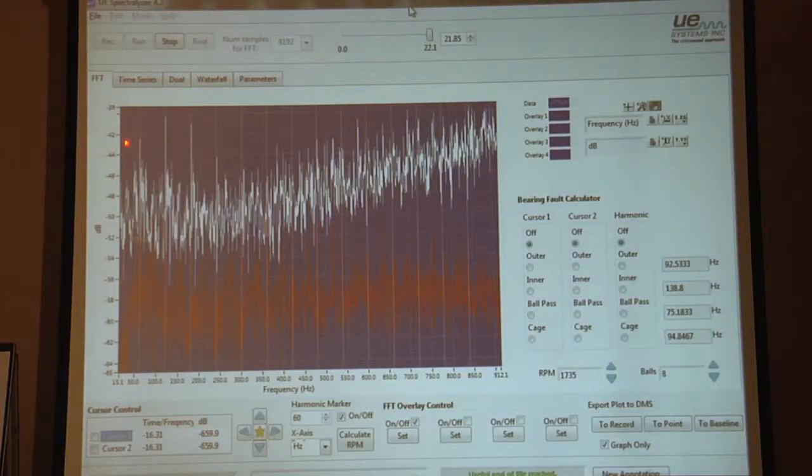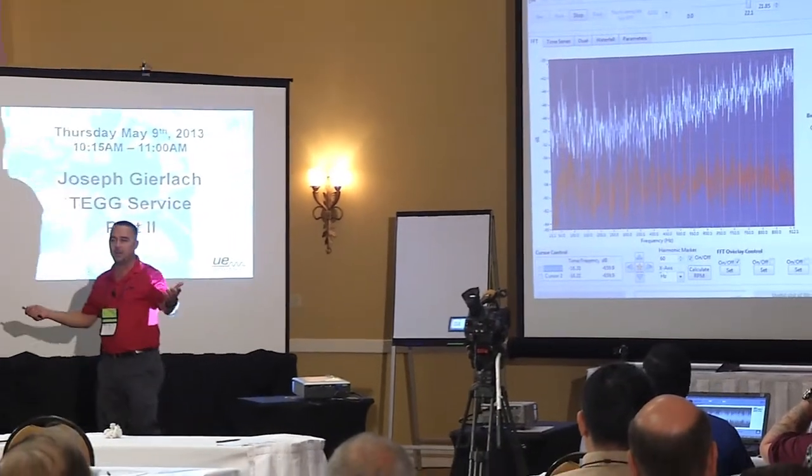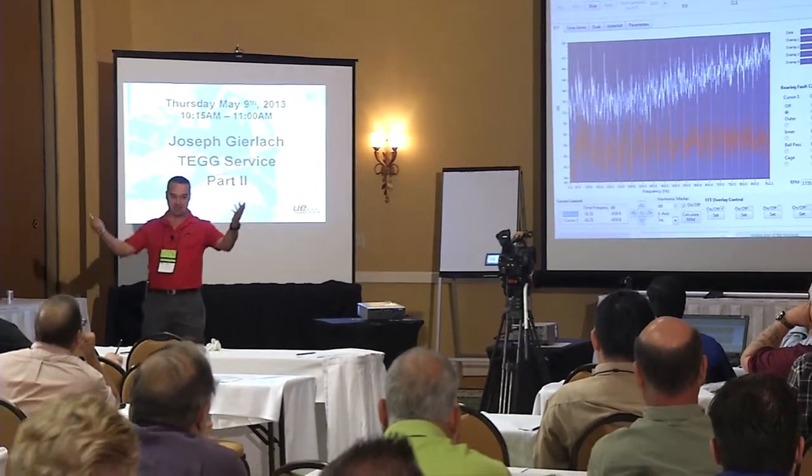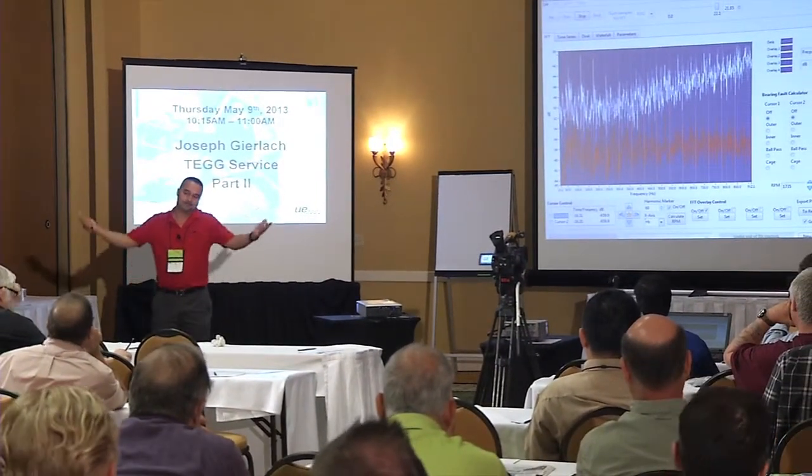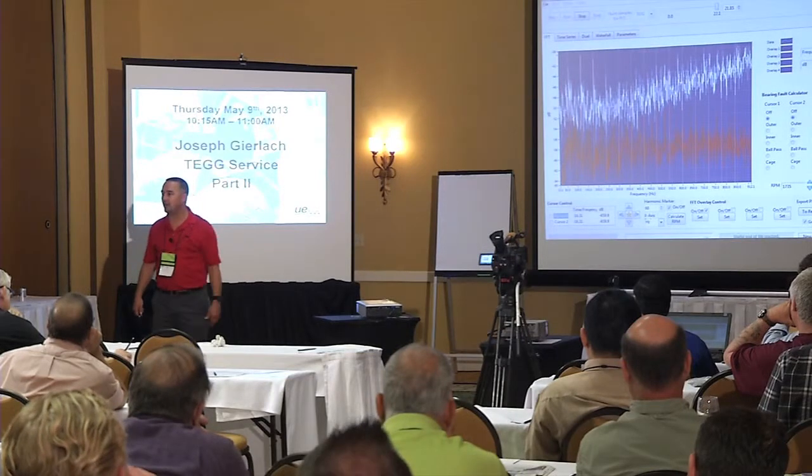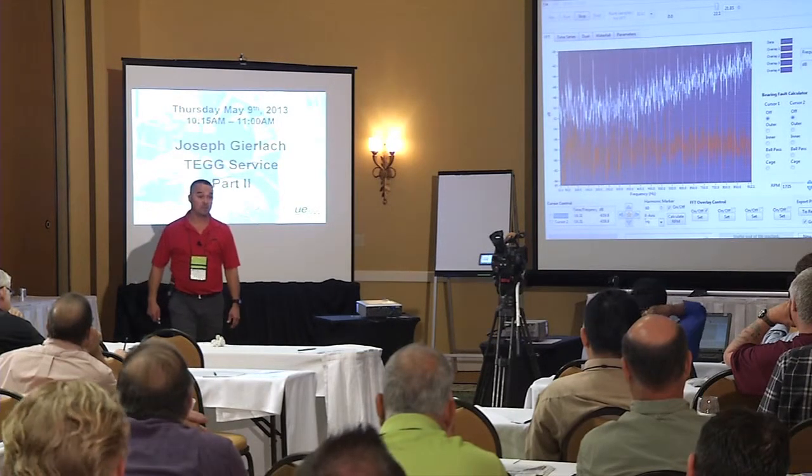Well, we still have this 60 hertz harmonic, this one, and then look what happens further out. It starts to not hit directly on the 60 hertz harmonic, right? Whereas the corona hit every 60 hertz harmonic. So Mark characterized it as we're masking or losing, dropping off the 60 hertz harmonics out here on the spectrum, but the frequency noise remains. I mean, how many do you have to lose before you say, hey, this is now destructive? You hear the popping and combine it with the losses of 60 hertz harmonics, it's probably destructive at that point.